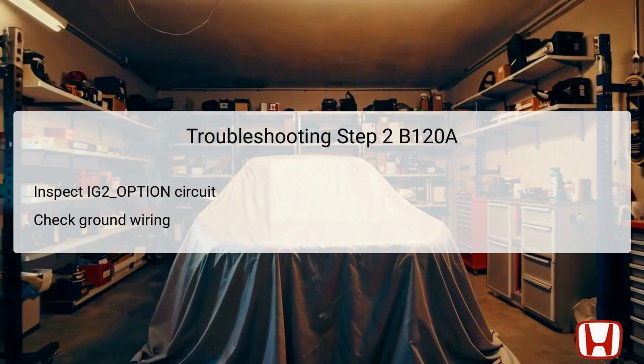During this inspection, the technician should refer to the electrical schematics to verify the integrity of the connections and correct readings. Should any abnormalities be found in the circuit inspection, it necessitates immediate attention to avoid prolonged issues with climate control functionality. In this troubleshooting step, the focus shifts to testing the bus data connections.